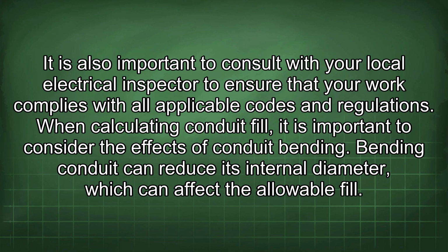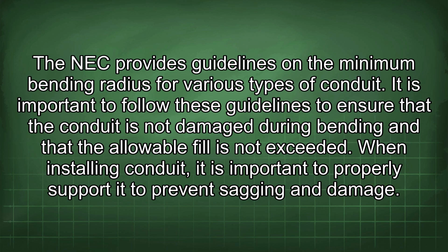Bending conduit can reduce its internal diameter, which can affect the allowable fill. The NEC provides guidelines on the minimum bending radius for various types of conduit. It is important to follow these guidelines to ensure that the conduit is not damaged during bending and that the allowable fill is not exceeded.